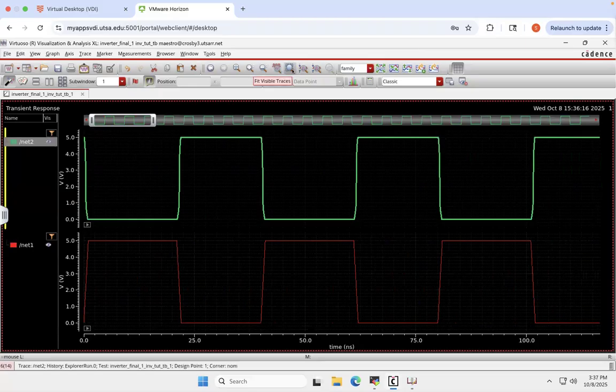Okay, as per different assignments, you can choose which signals you want to display. Okay, you can save these signals as well, save this output file as well, or you can choose not to save. So every time you need this output file to be displayed, you can just do simulation, netlist, run.